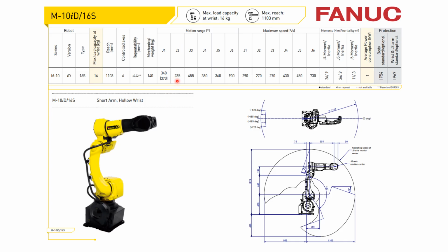That means up to what angle these can be moved, rotated or twisted. And the same with the speed, as we were discussing: at what maximum speed these can be moved, because they have servos or steppers, which are control devices, and they have some limitations. Along with that, they have some mechanical limitations on movement, and that's how the speeds are given, and then the moments are given.